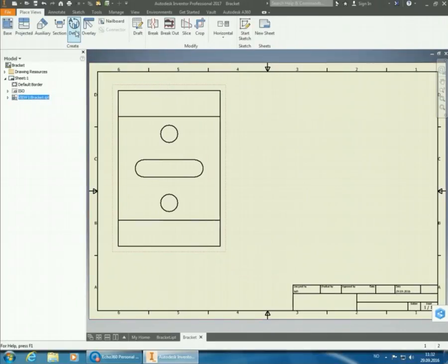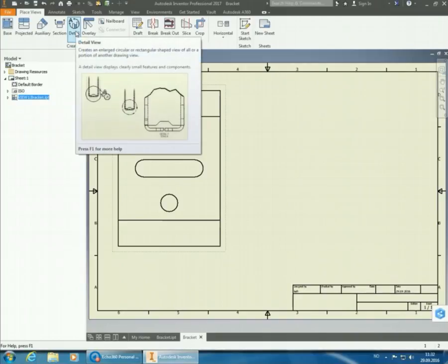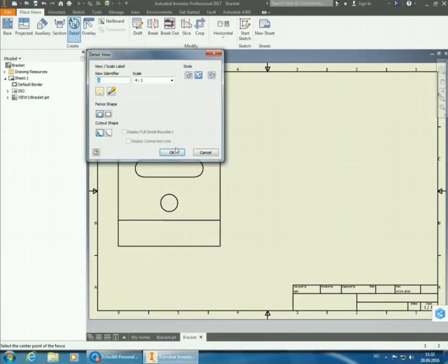And then we'll choose the section part. Now, if we just look at it straight away, it says that it wants to use a 4:1 scale on the section. But I used a 2:1 scale on this one, and that means a 4:1 is going to be twice the size of that one. So we can't have that. That's going to be way too big. So I have to scale it down to 2:1 so that we get the same one as the original.